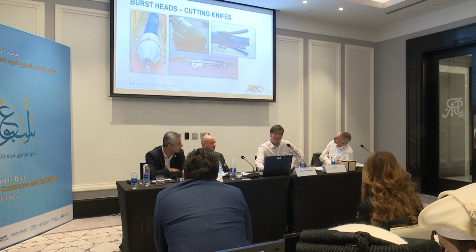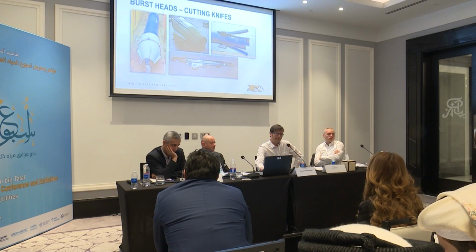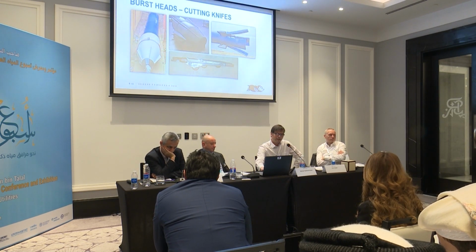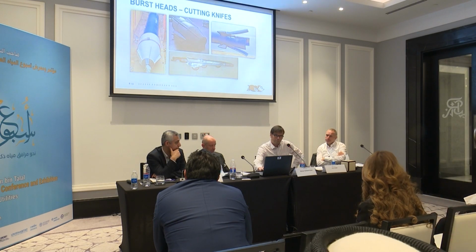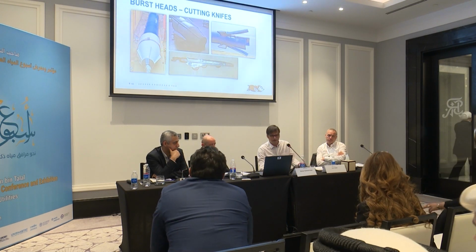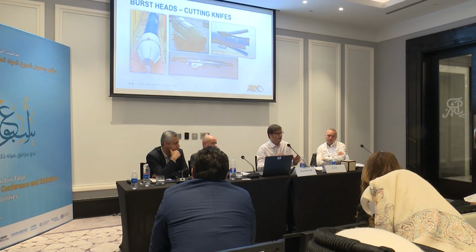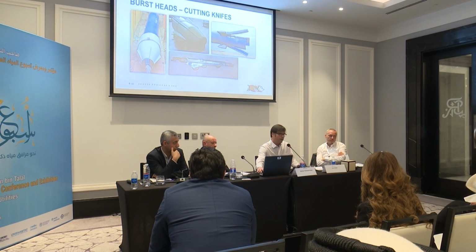We can use a roller blade where, for example, when you burst a ductile iron, you use that, or if you burst a cast iron that has been repaired very often, you can use the roller blade to cut through the repair clamps. So for every single material there is a specific attachment, a specific bursting head that allows you to get through that material.